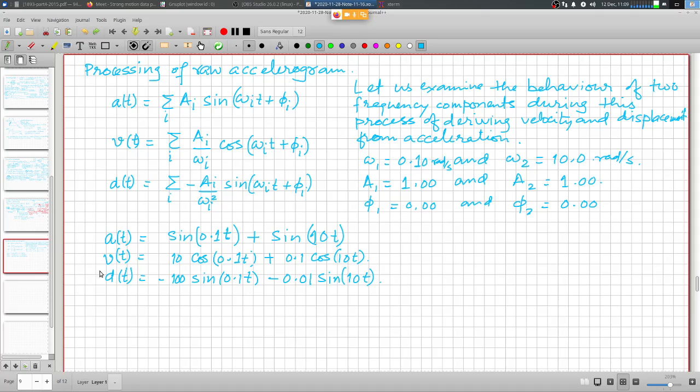So this effect is completely absent, or insignificant, so to say. The velocity is somewhere in between. You can see both high frequencies and low frequencies, but you will still see the differences. In acceleration, it is the high frequency which dominates, the lower frequency only provides the baseline.